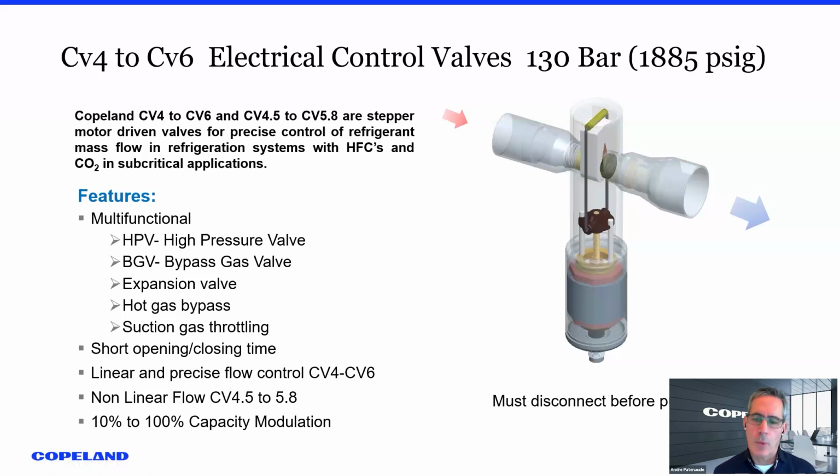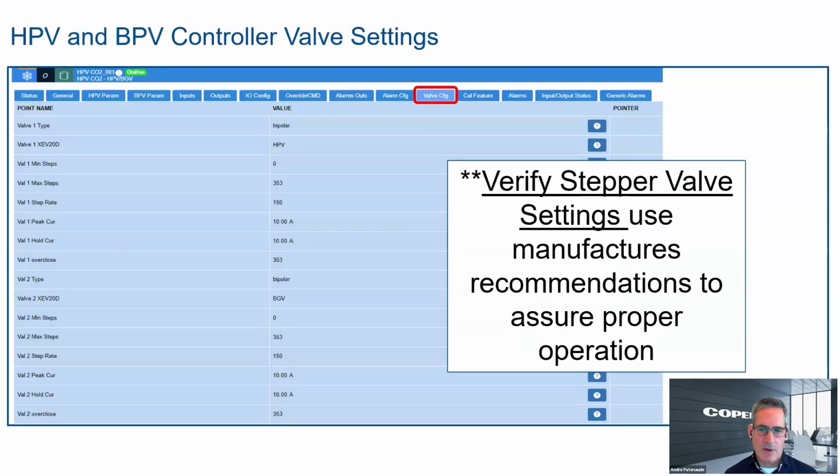So drive the valve open, disconnect the plug from it, pull your vacuum, and then you can reconnect it after your vacuum's completed and you've got some vapor charge in there. So you don't want to damage a valve for no reason.